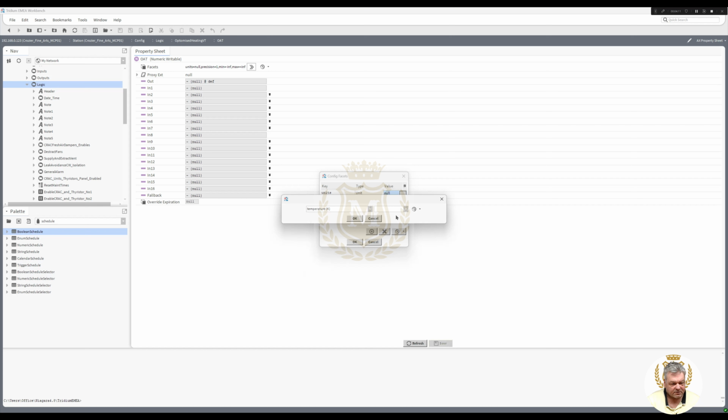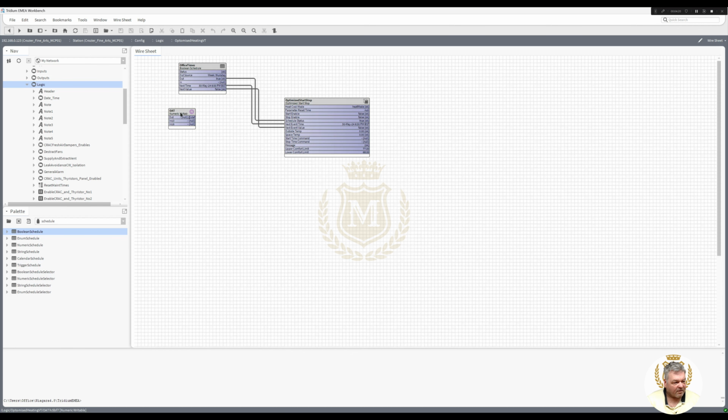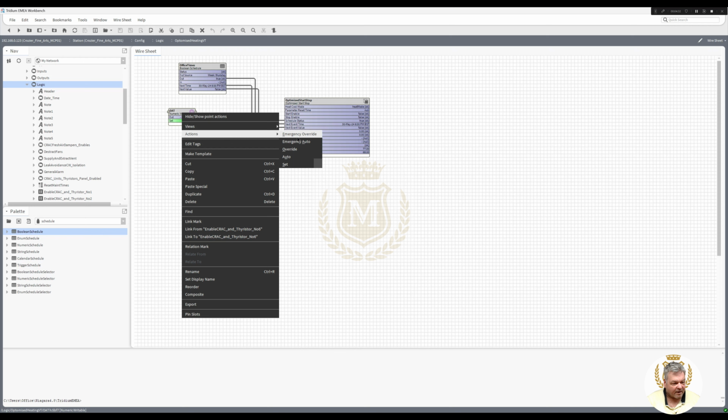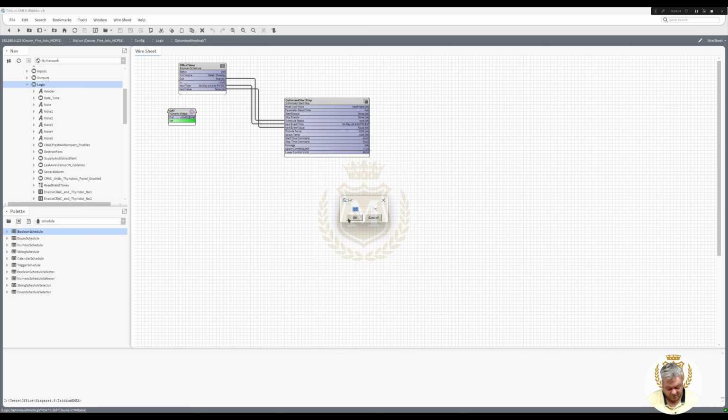Are you there? Put you to Celsius. Okay, we'll leave it at 1 decimal place. Save that, and we'll take out the in 10 and the in 16, and just have the set, so we can just play with the values. Action set, and we'll set the outside air at say 14 degrees for the moment.